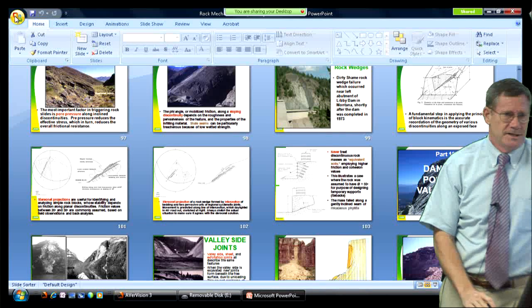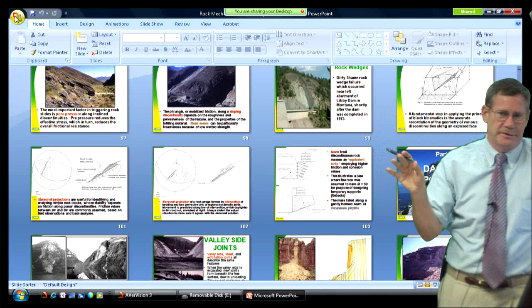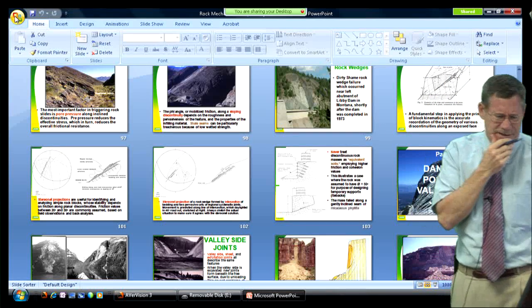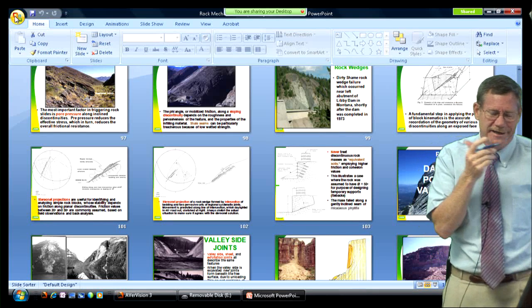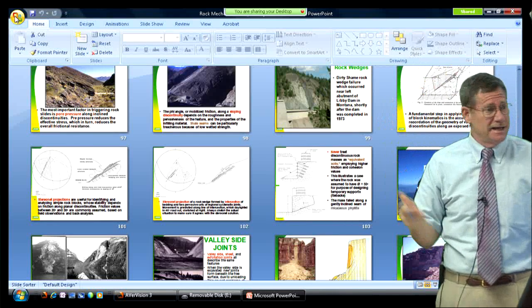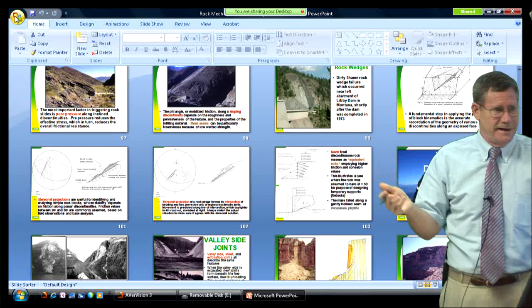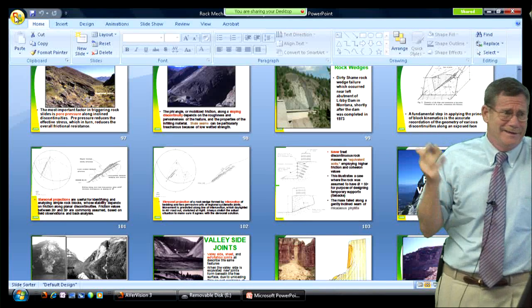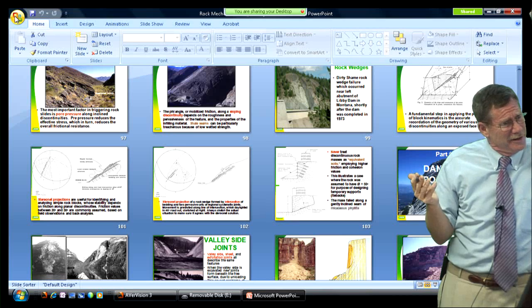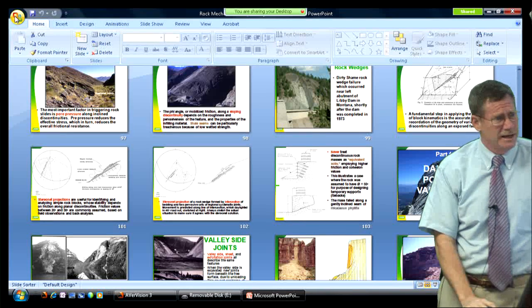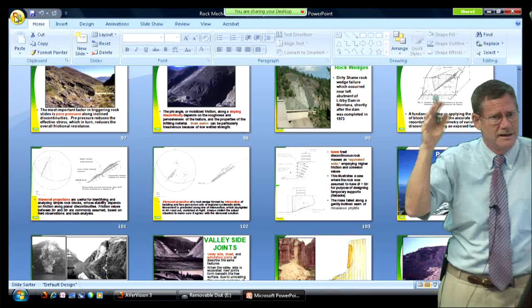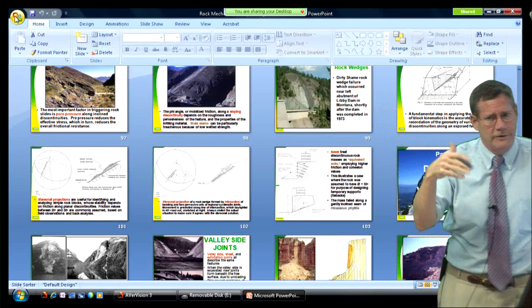And there's your problem. Wherever we go out on a rock slope and scale it, and this happens all the time in urban areas. We had a case in San Francisco years ago that I arbitrated as the judge. They had done all this scaling, and guess what? 17 years later, another block came off and careened into a restaurant and creamed it. Well, duh. You did a tune-up on your car and put a full tank of gas in it, and how's it doing 17 years later? You had 17 years of weathering, of freeze, thaw, and creep, and water going in, water going out, and load.